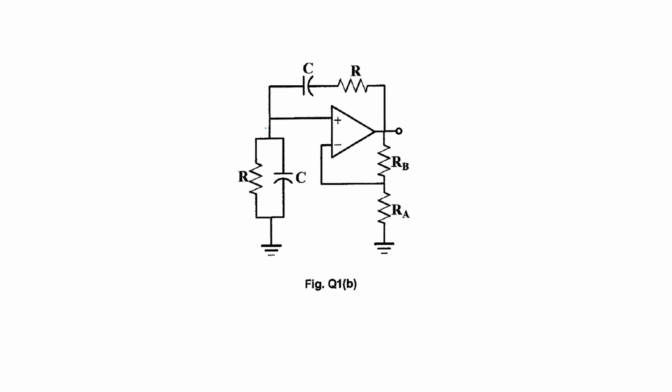Now, if you look at this thing, you have an input here. So this here could be an input here. This here, the output. So by carefully selecting the values of R and C here, you satisfy the Barkhausen criterion. And well, the amplifier, of course, is just to sustain the gain.